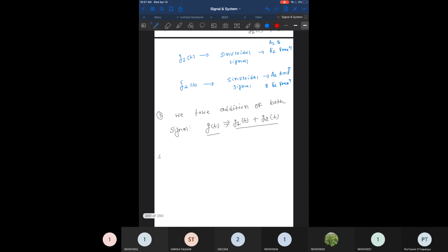And then finally we take the Fourier transform. We can plot this graph also. This is the plot of g of t with respect to t. Then we will take the Fourier transform, and for the Fourier transform in MATLAB, a direct command is available, that is known as FFT.